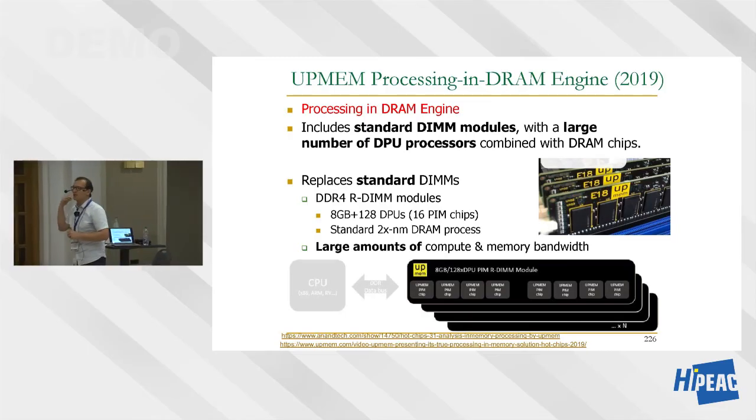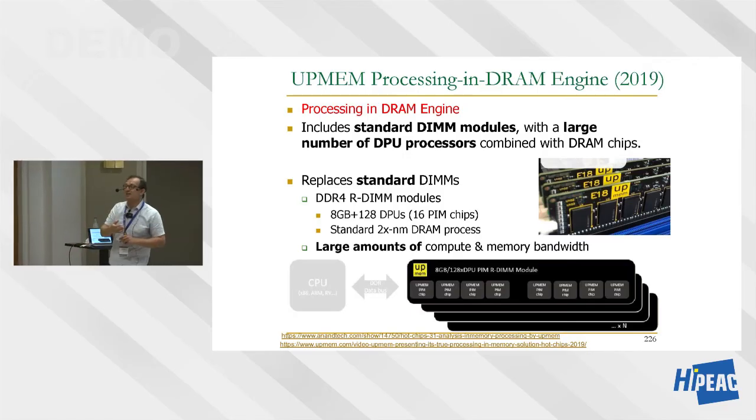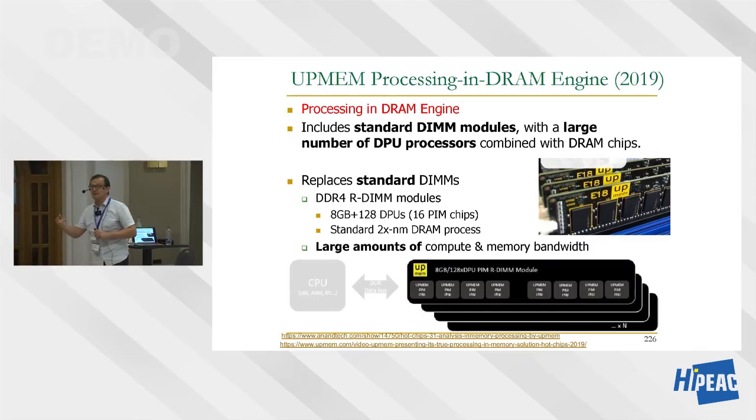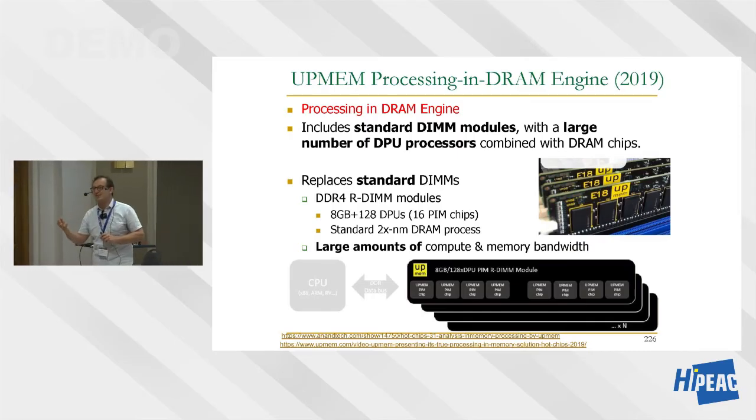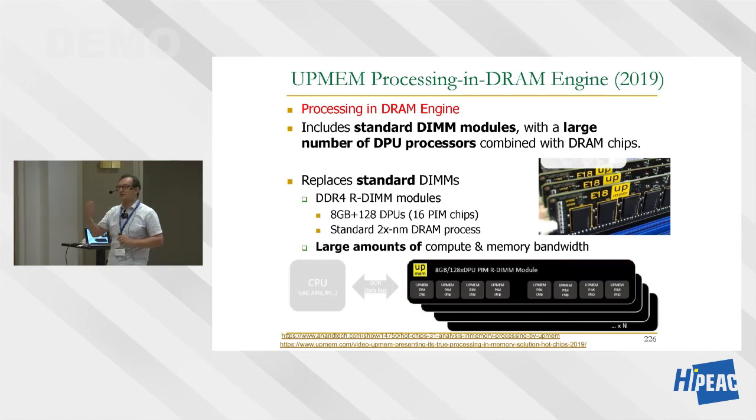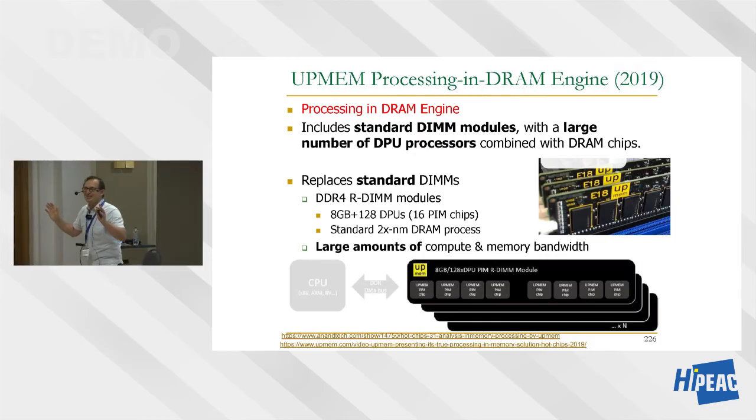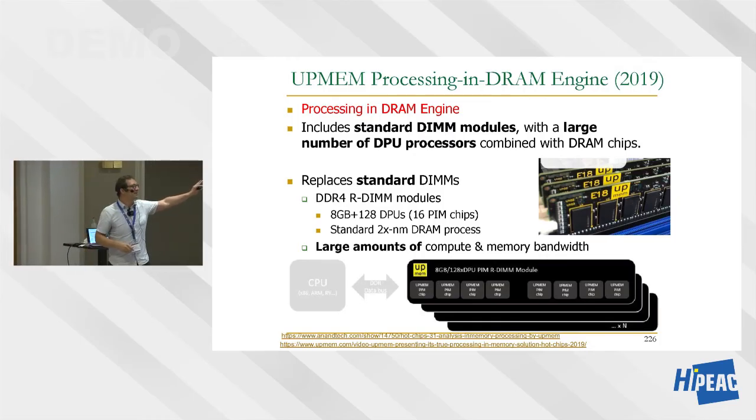And the other thing is, there are some design choices over here that I don't want to pick on, but the instruction set doesn't support multiplication instructions that are larger than the granularity of 8 bits. So the best you can get is 8-bit multiplies. If you want to do 16-bit multiplies, it's a lot more costly. If you want to do bigger multiplies, good luck. So basically, this is not good for especially workloads that exercise multiplication a lot. And there are some workloads like that, as you may guess. Like machine learning, right?